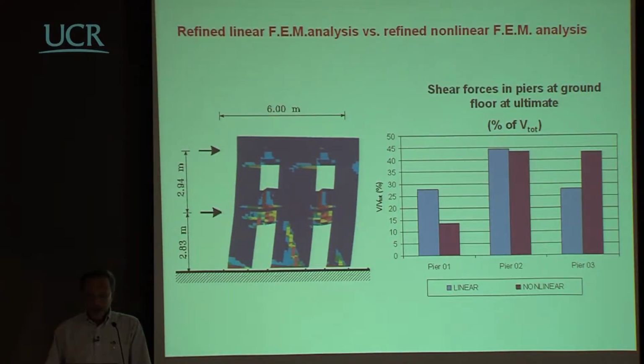And in fact, if you look at a case where you're simply doing a pushover analysis of this sort, just pushing in this direction, you can see that the amount of shear that this part of the wall is taking is much higher than the shear that this wall is taking.